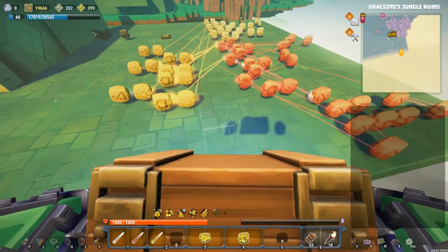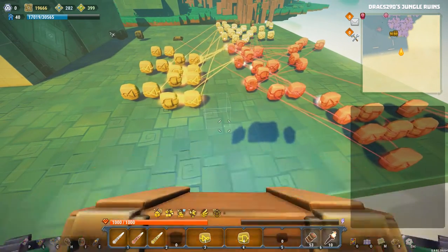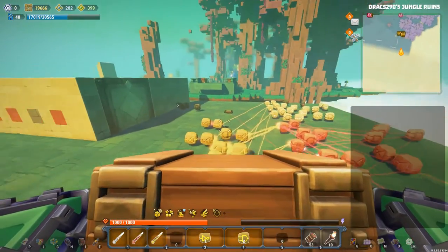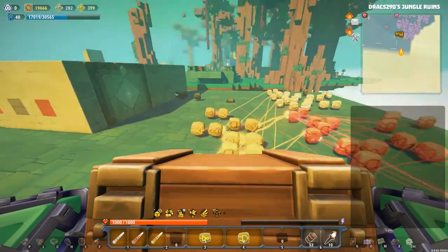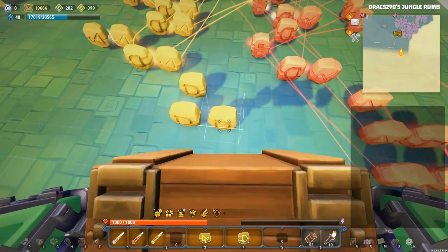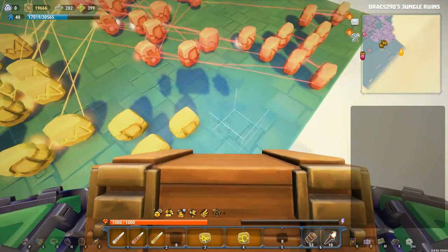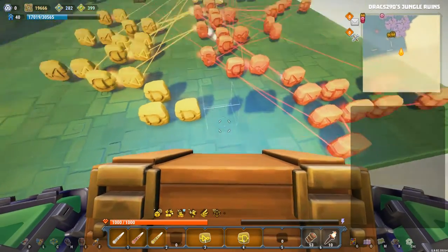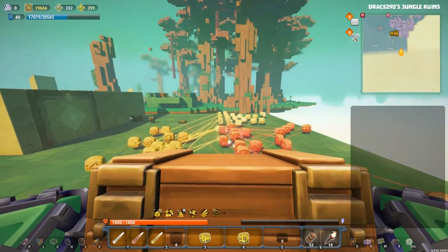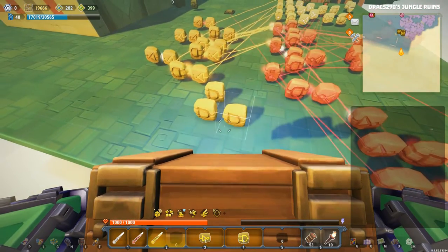But at the same time, we're going to just quickly place down. So we need two AND gates, I should say, to hook up all of the latches or all of the nodes and the input. And then we're going to need an AND gate to connect those all together. And then we're going to do a quick little rising edge pulse to then reset either the counter or the sequencer. I think we'll reset the counter with this one though.